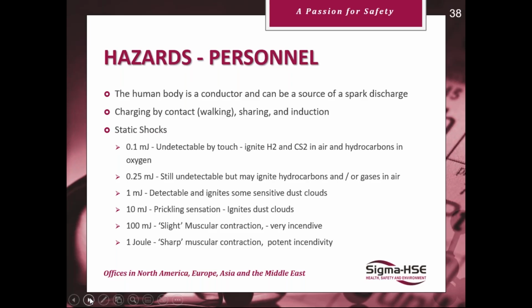With personnel, the human body is a conductor basically, and you can have spark discharges. We've all had them. I don't know anyone who's never had an electrostatic discharge. You can get it from walking, sharing, induction. If you want to know certain levels: 0.1 millijoules is undetectable by touch, but it still ignites hydrogen and carbon disulfide in air and some hydrocarbons in oxygen. 0.25 millijoules is basically undetectable by us, but may ignite hydrocarbons and gases in air.